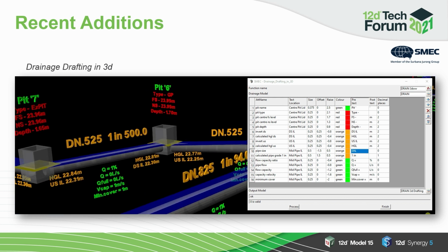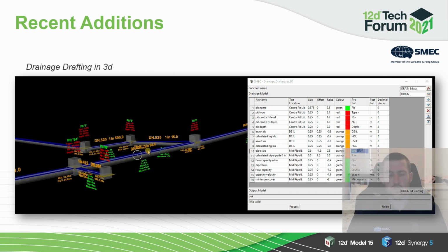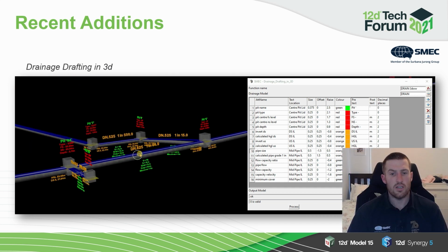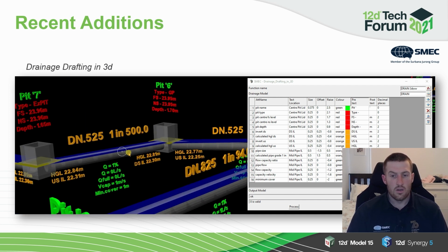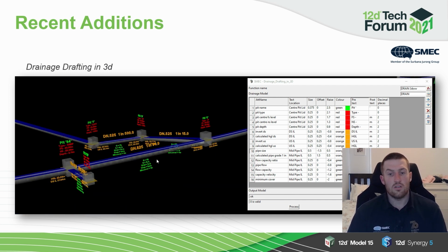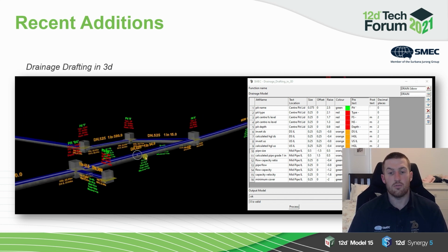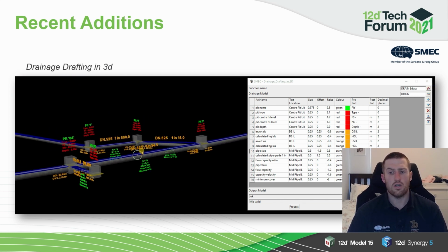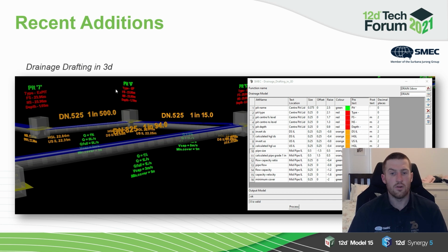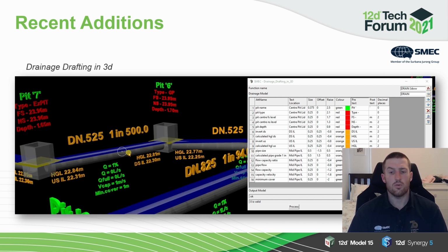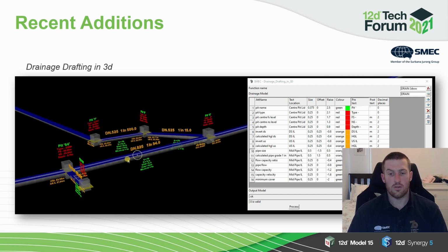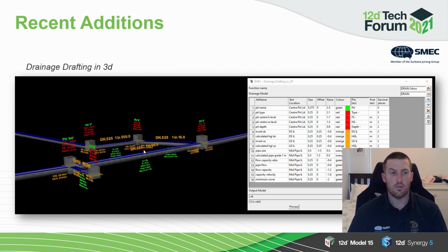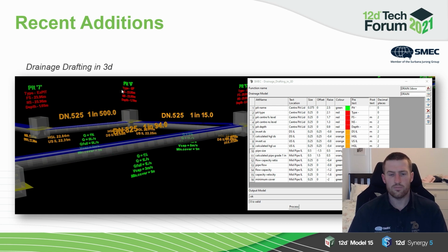User can also select the text size, offset, your typical things, the rise, the color, pre-text, post-text, and a number of decimal places. Again, this macro allows the design checkers to view information usually found on the drainage long section in a BIM model. And as I said, hopefully this can help the quest to removing the need for drainage long section drawings, and hopefully it's another step in the right direction to removing drawing sets altogether, maybe one day.